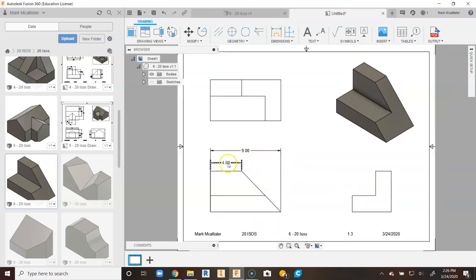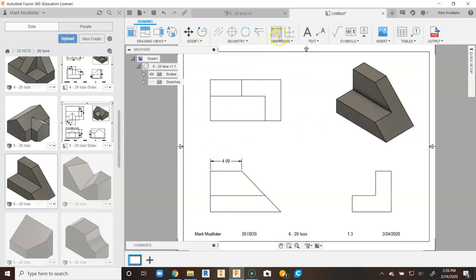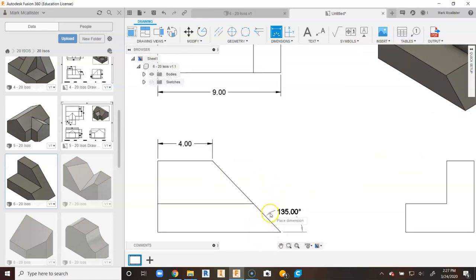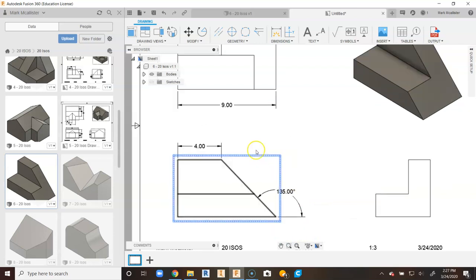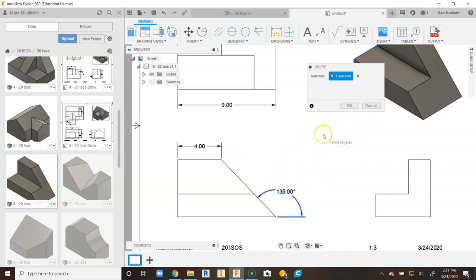I'd tell you what, for the sake of the way this looks, we'll just go ahead and keep it the way it is right here, which is fine. You could make another argument, which I could totally understand. You might say, you know what, I don't really think that we should place this here. I think we should place this up here in the top view and say, from here to here, let's place that up here in the top so this is totally open. And if we chose to come in here and do some kind of an angled dimension, I could say 135 degrees here. You know that 135 plus 45 is going to equal 180 degrees, which is a straight line. So we could place that there and ignore the 9 if we wanted to, but we'll go ahead and delete this.